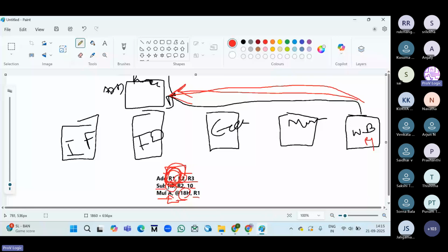So to execute this instruction, suppose there is an add R1, R2, R3. That means first of all we need to fetch these R1, R2, R3 values. Whatever the register values, or immediate address, or index type of instruction set. There are different types of addressing modes and instruction sets, right? If you remember, all the data we are fetching in the instruction fetch stage.